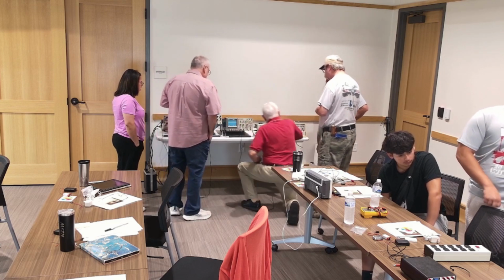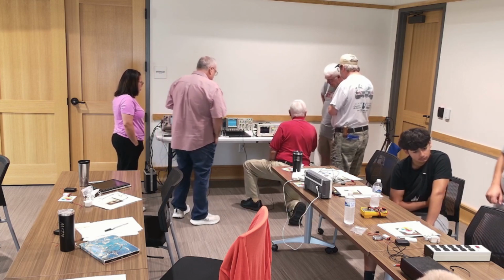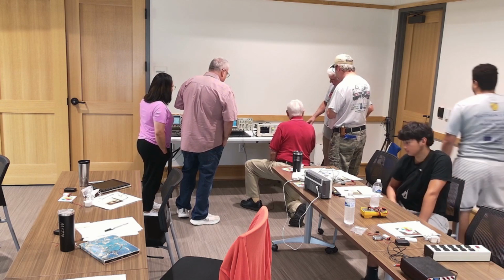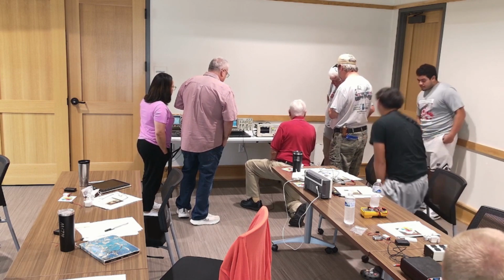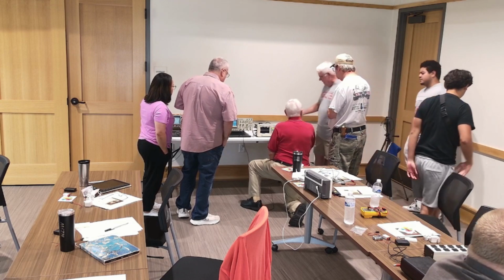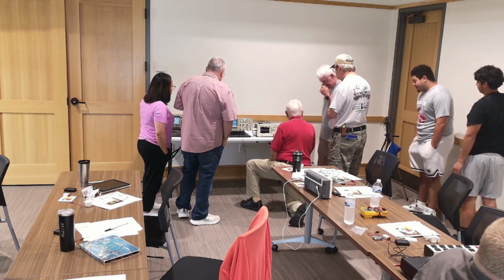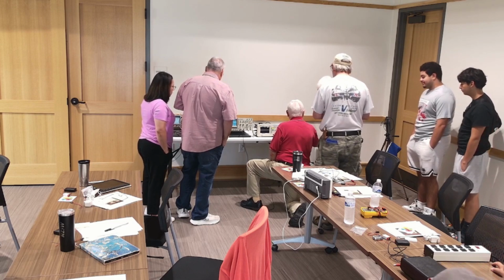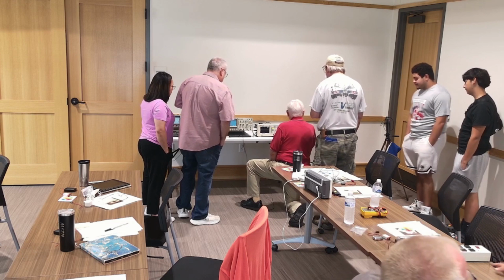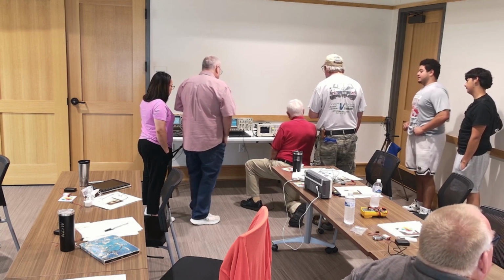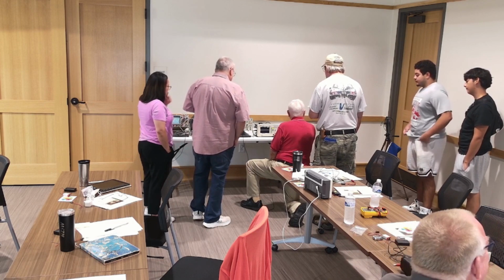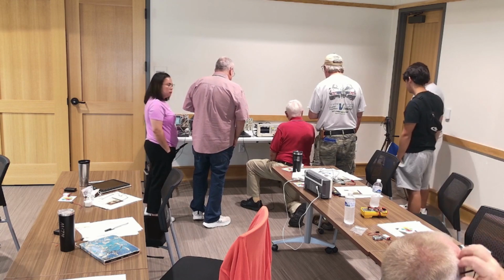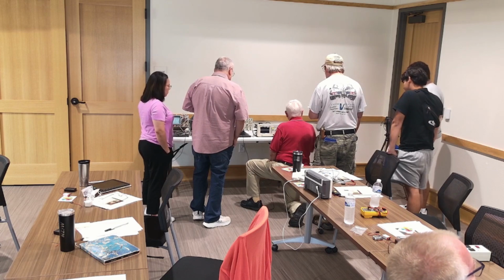Right now he says he is on sine wave. This is the frequency generator? It's a frequency generator. I'm running in generator mode. This is also a counter, but right now we're using it as a generator. It's just plugged into AC, that's all. Okay, so we're on the 2 megahertz scale. We can change it a little bit. Let's take it down to 200K and see if we can generate about 200 hertz. That's close.